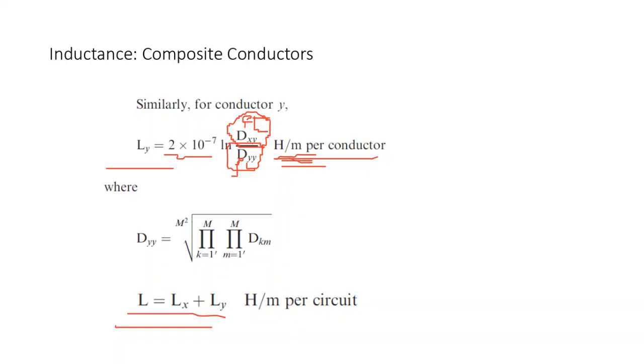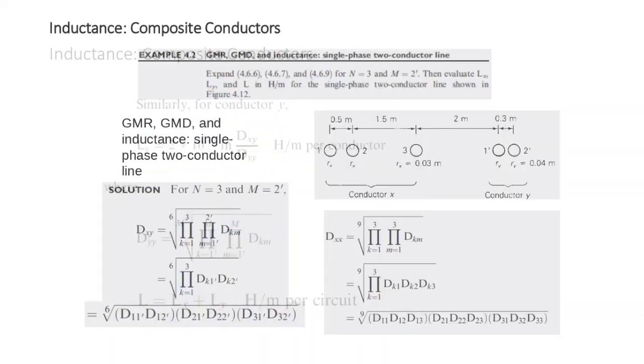That's what you will see in the mosque, and some houses also, if they have more than 2.5 ton. 2.5 is single phase. 2 is single phase. 1.5 ton is single phase until 2.5. If they go higher, then they need a 3-phase system.